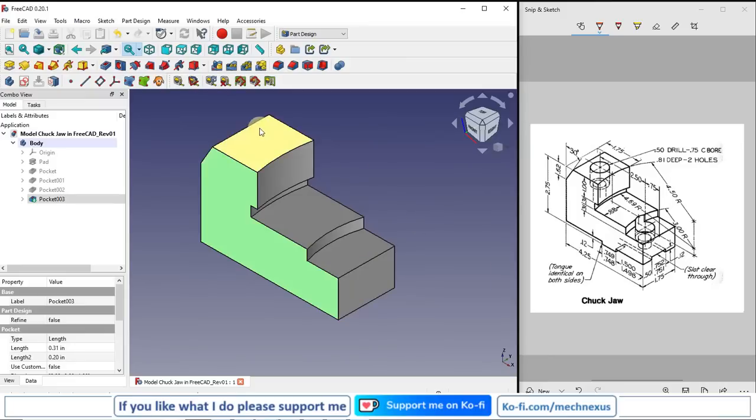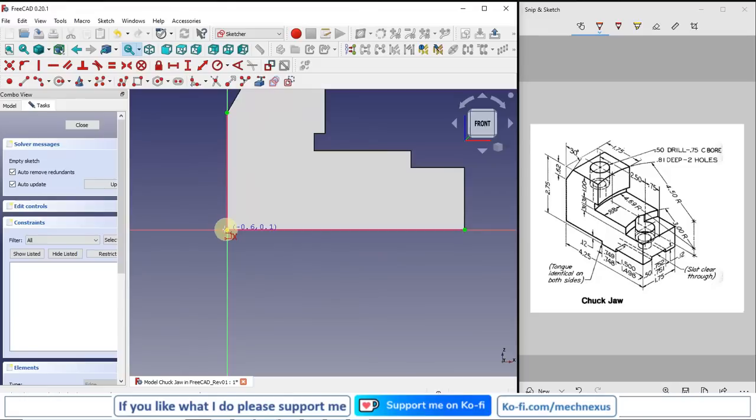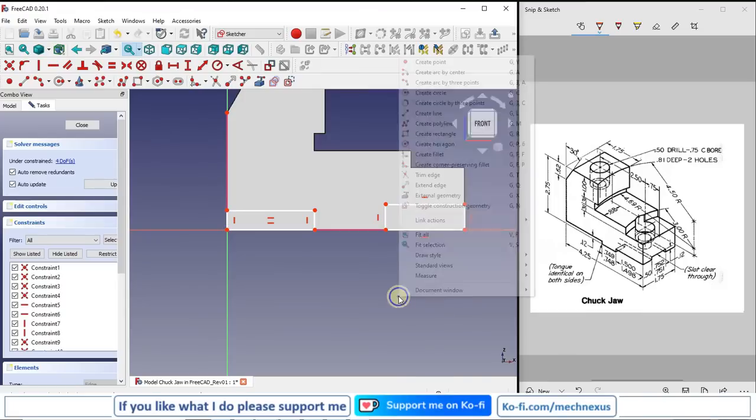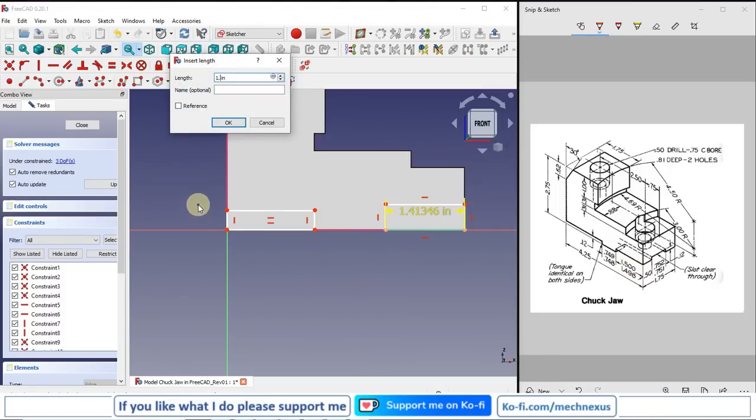So I will select this face and I will say sketch, and I will project these two edges, and I simply draw two rectangles from here and from here, and now we will read the dimensions and we will constrain it. So if we see here, from here it is a maximum 1.5, so I will give it 1.5,